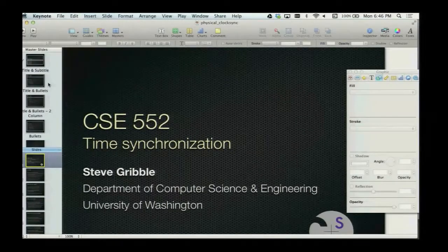They are magic. But roughly the way to think about it is a clock crystal is basically a quartz crystal that has this property called piezoelectricity, and I don't know a lot about this, so I'm going to be doing the best that I can here. But roughly think of it as this lattice of atoms, and that entire clock crystal can oscillate. So the distance between them can fluctuate, and there's a whole bunch of different ways that it can oscillate, but there's some dominant mode that it likes to mechanically oscillate. And if you start oscillating in that dominant mechanical mode, the fact that it's oscillating actually causes a little miniature electric field as a result of that.